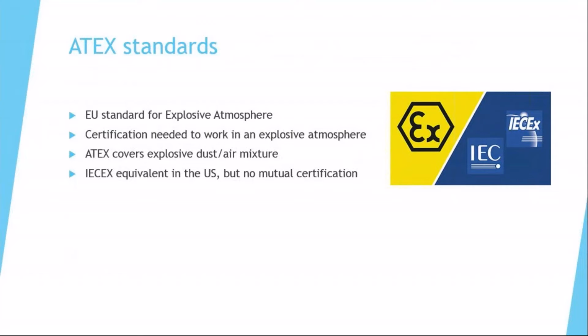The main limitation is in Europe, and they are mostly the same in North America, are the ATEX standard and certification, which is the European Union standard for explosive atmosphere. This certification is needed to work in an explosive atmosphere, which is a definition of some areas in the plant that are supposed to have some contaminants or are exposed to contaminants.